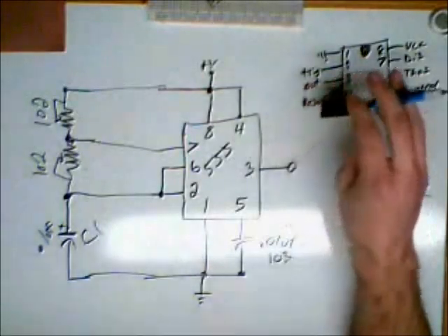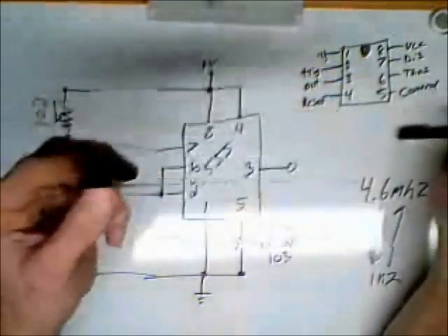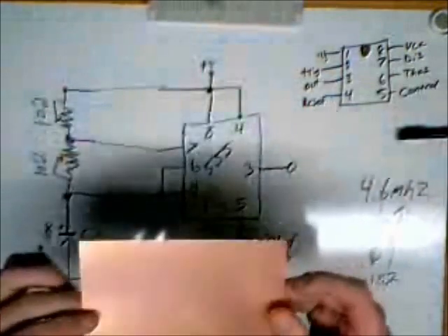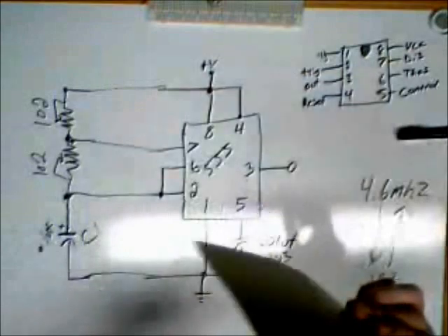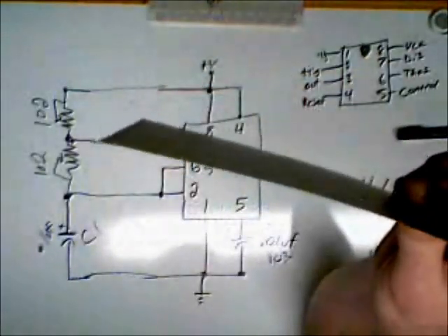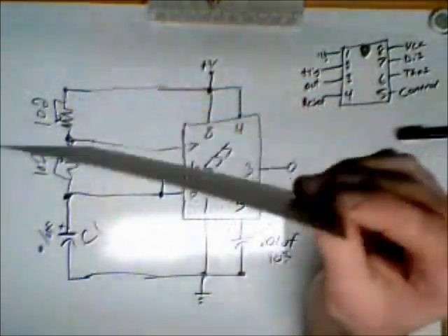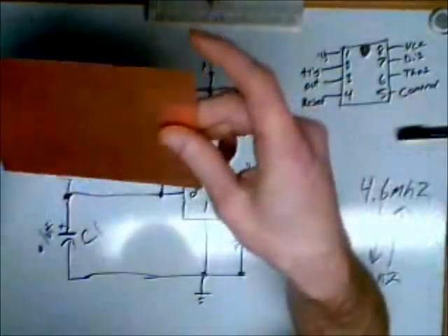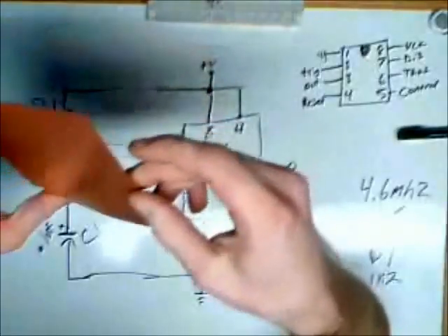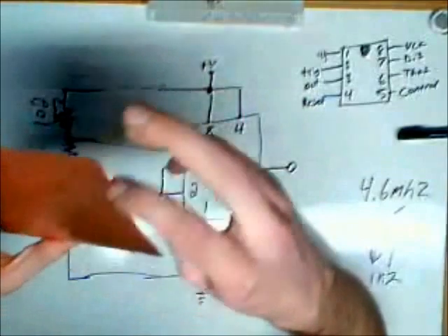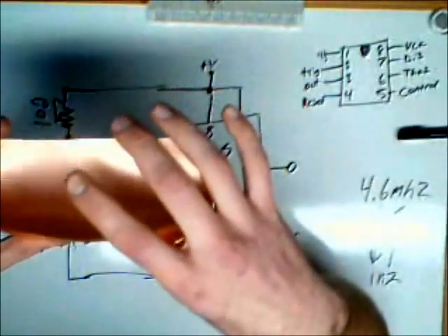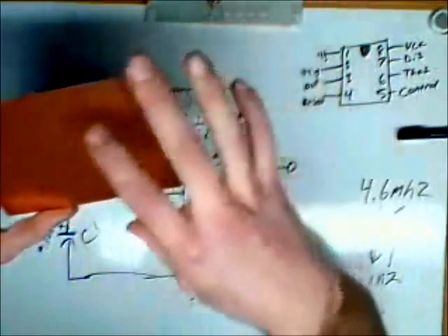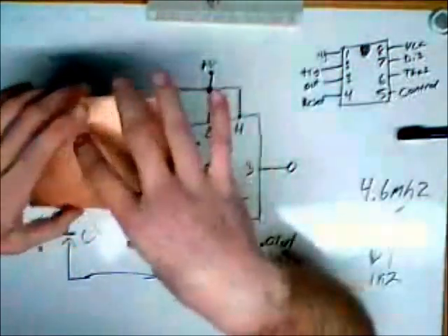I'm going to actually etch it onto a piece of laminate copper clad sheeting I got. It's really thin. It's about as thin as paper, and you can cut it with scissors. So I'm going to try etching it, and to etch it I'm not going to actually print out anything and copy it on there, heat stamping or any of that. I'm just actually going to draw out my schematic and how I want it connected, and use a Sharpie to define my traces and try to etch it and see how that turns out.